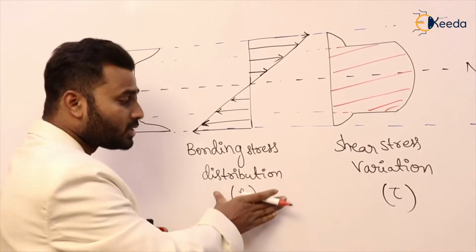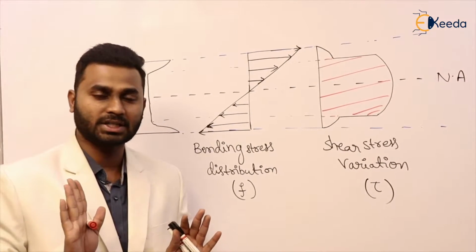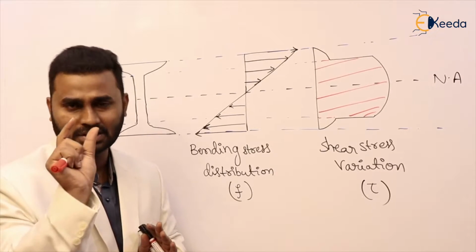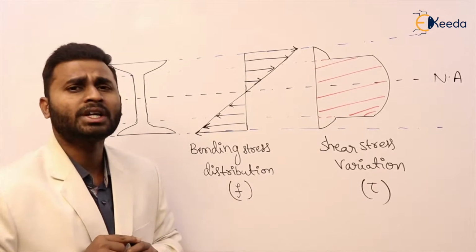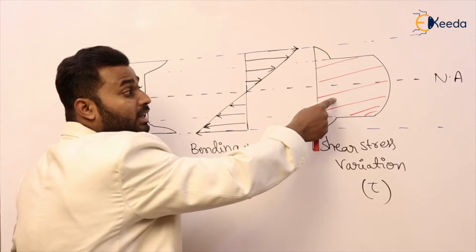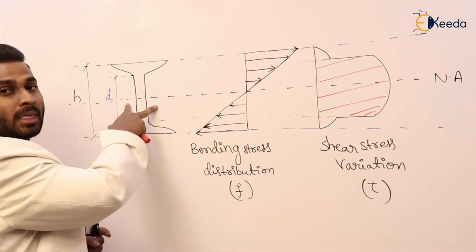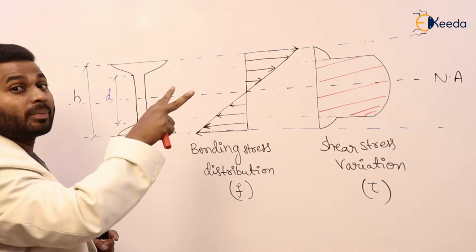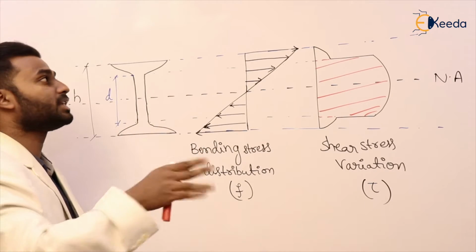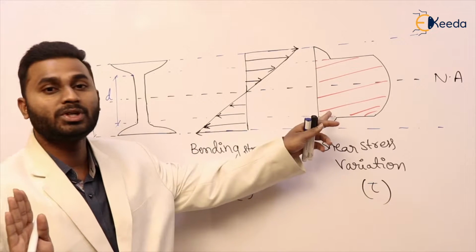Now, based on this concept, as I said, this is the concept of strength of materials. Of course, we are not discussing the working stress method here, we are discussing only the limit state method, but this is required. In the working stress method, we assume that 90 to 95% of shear is resisted by the web itself, and 90 to 95% of bending stress, or flexure, or bending moment, is resisted by the flanges itself. Those are evident from the stress distribution.